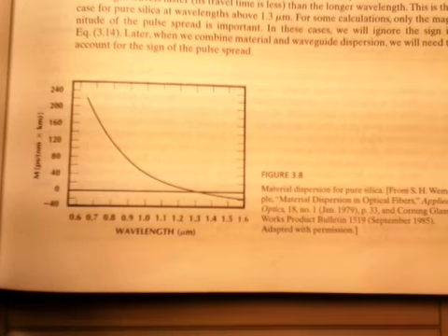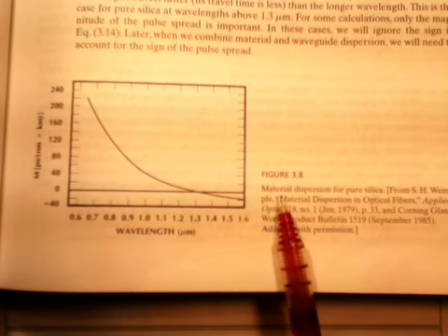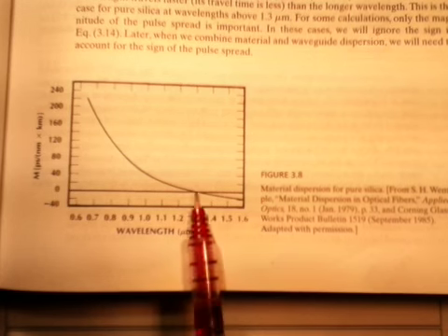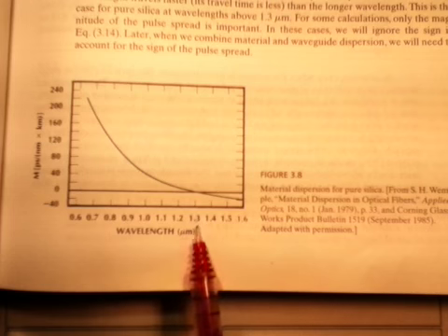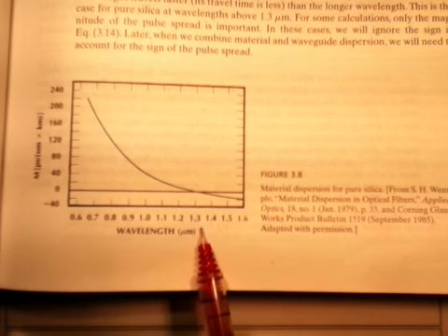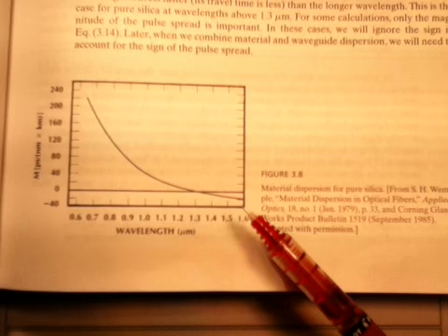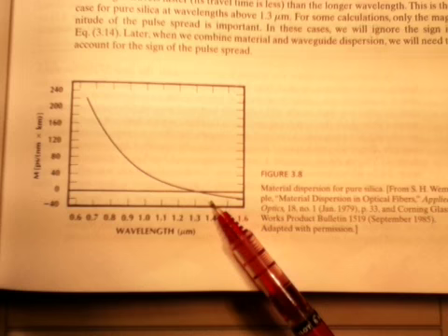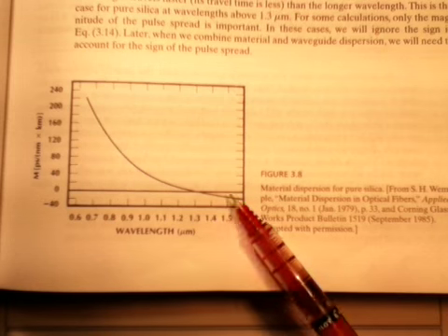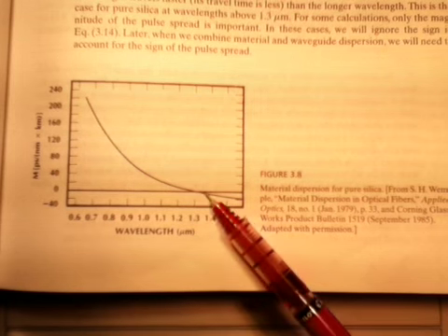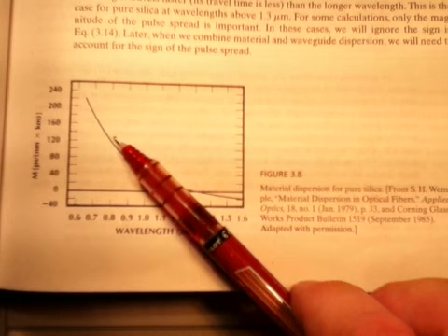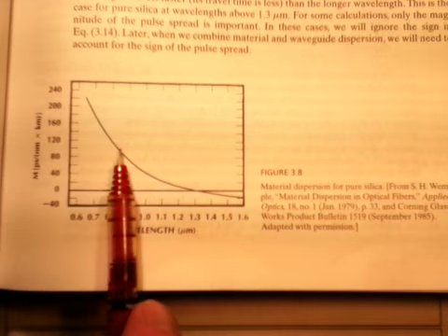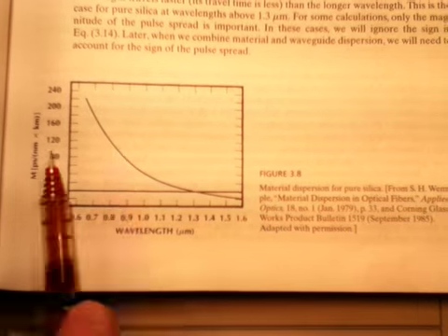On page 69 we have the material dispersion plot, and you can see that material dispersion really does have a zero dispersion wavelength at 1300 nanometers, or 1.3 microns, and that it's as high as about minus 20 picoseconds per nanometer kilometer at 1550, and it goes up all the way up to several hundred, or at 850 nanometers, it's up near 90 or 100 picoseconds per nanometer kilometer, quite large there.